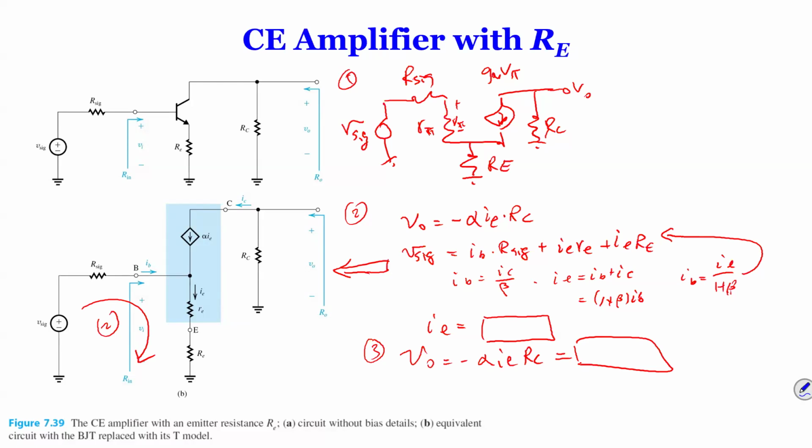What we're going to do is look at, again, the input and output resistance. When we look for the input resistance, you need to short the voltage and open the current, but there's no other voltage or current source in the circuit, so there's nothing to open other than the control source.